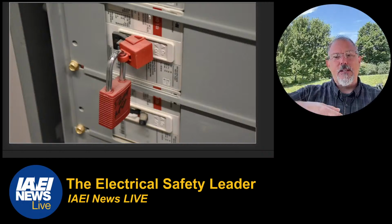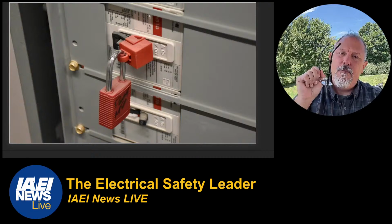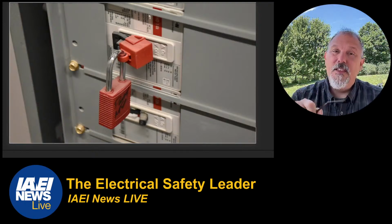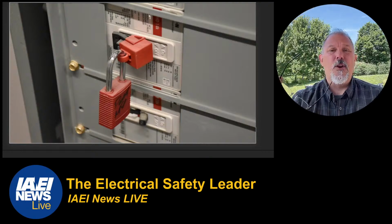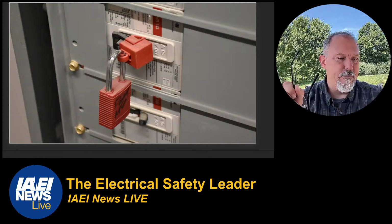So you have a lock, you're going to place a lock on a piece of equipment, and I know some of you are going to say, wait a second, Tom, that method is not going to remain in place when that lock is removed, so it doesn't meet the requirements in the code. But remember, there are many cases where you will use a lockout method that's not required to have a lockable means in place because it may not be required by the National Electrical Code. So there's no requirement for the lock method to remain in place when the lock is removed. So in many cases, these types of devices are perfectly legal. So remember that.